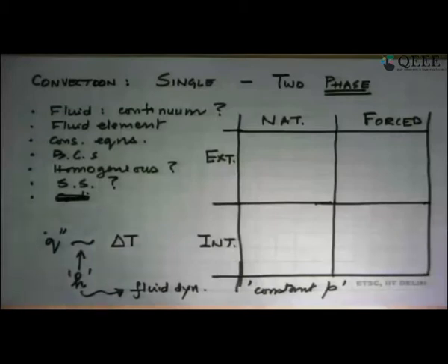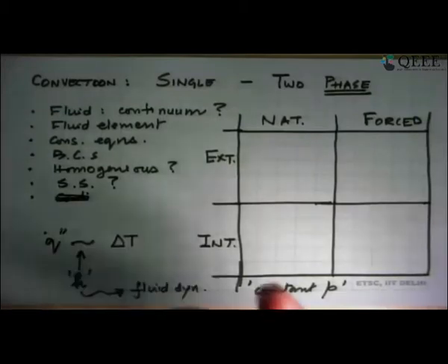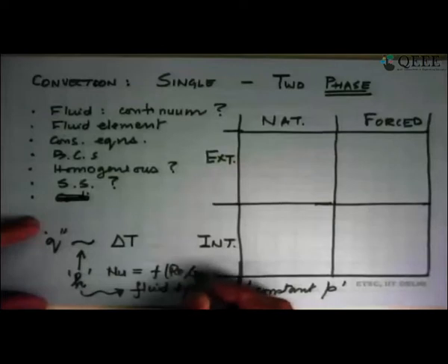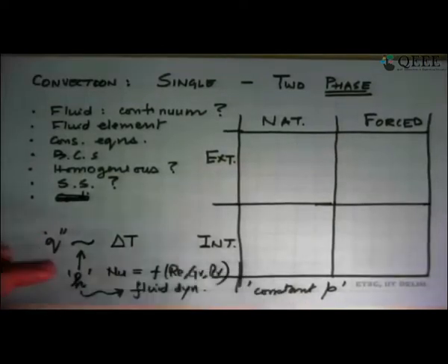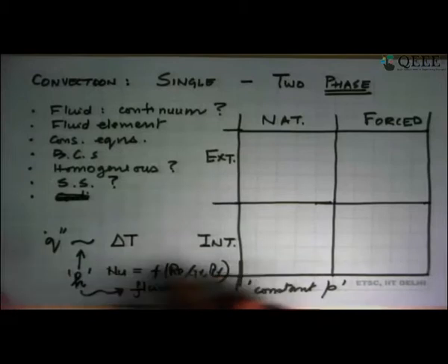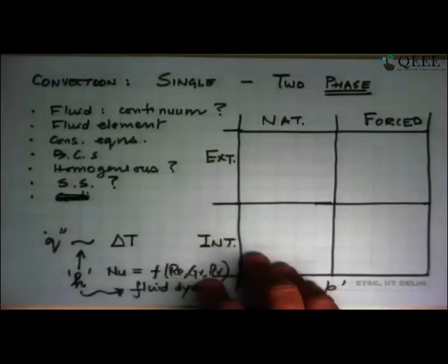And we came across the differential equations by which we could solve them. I also mentioned that in many cases where the equations are not possible to be solved, we do a lot of experiments, and based on experimental data, we develop the answer for h in the form of a correlation, as a function of, say, Reynolds number, or yesterday we saw Grashof number and Prandtl number. And this is the solution to those conservation equations, which in non-dimensional form we can use in a variety of problems, and that is how we solve problems.